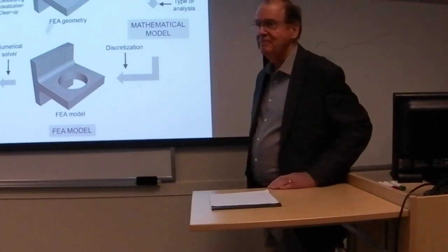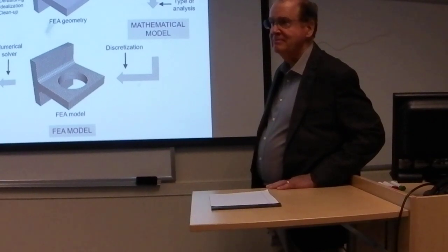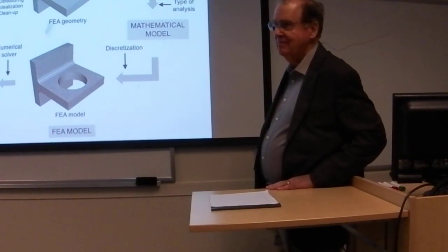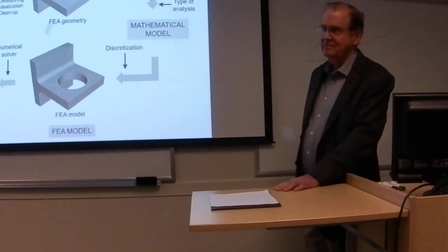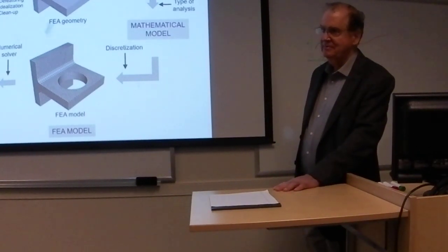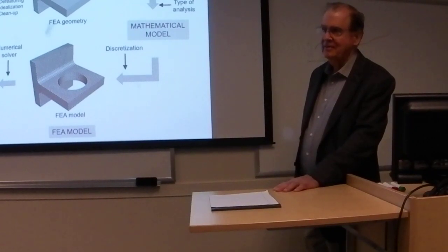Then with your loads, your restraints, material properties, and analysis, aka your boundary conditions, the biggest point of this is that is the greatest source of uncertainty in the FEA process, the approximations you make when constraining your model and when loading your model, and the math models that you use to run your calculation, and the errors associated with your mathematical models. And then you have the actual calculation that takes place, and that accumulates errors, and then you have the FEA post-processing or visualization, in which case you may get errors in how the color contour plot actually demonstrates or visualizes the actual stresses.